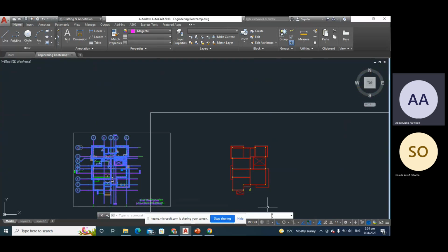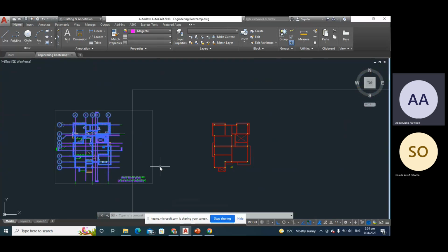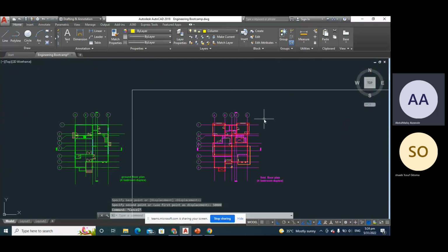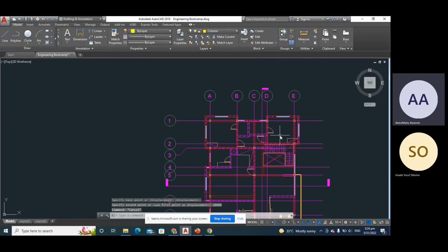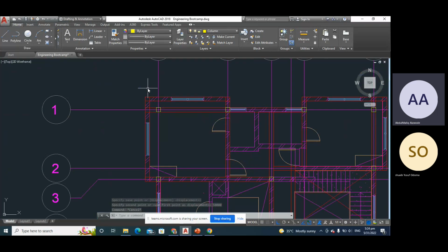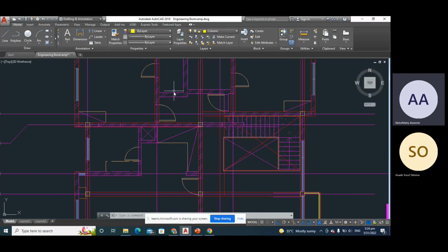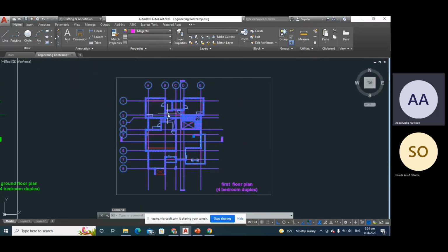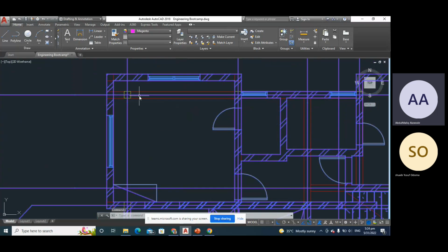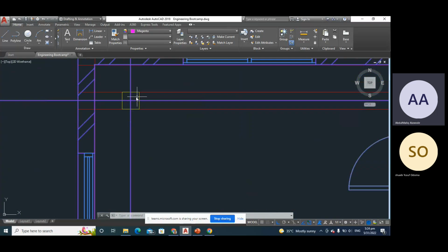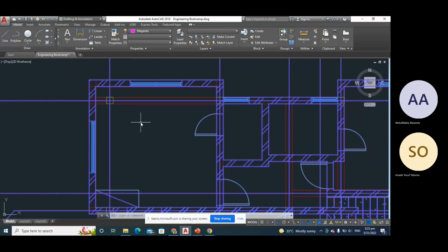So what we do next is take our first floor plan and put it on top of this first floor structural GA that we have prepared. So we now see the columns that cannot go. Columns that cannot go, we strike them off. That's the first thing we do. Now you can see this guy. You can see this guy is so unfortunate, it cannot go. Why?